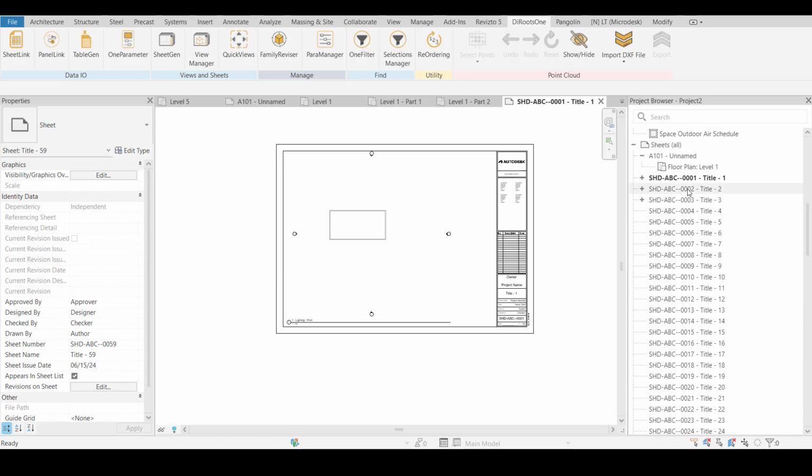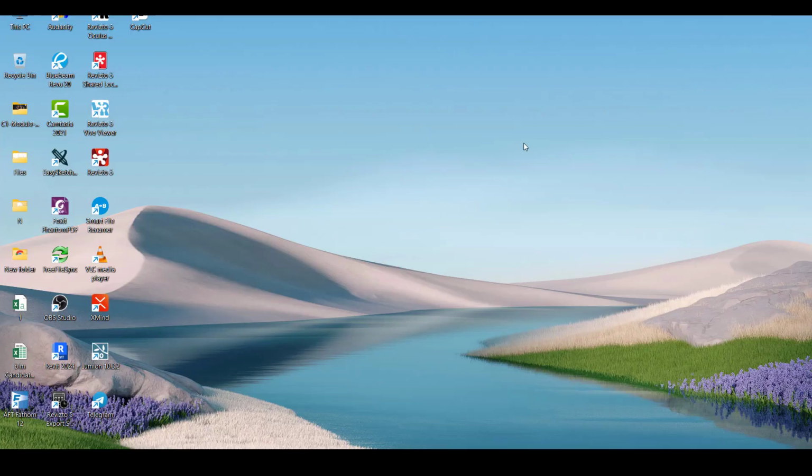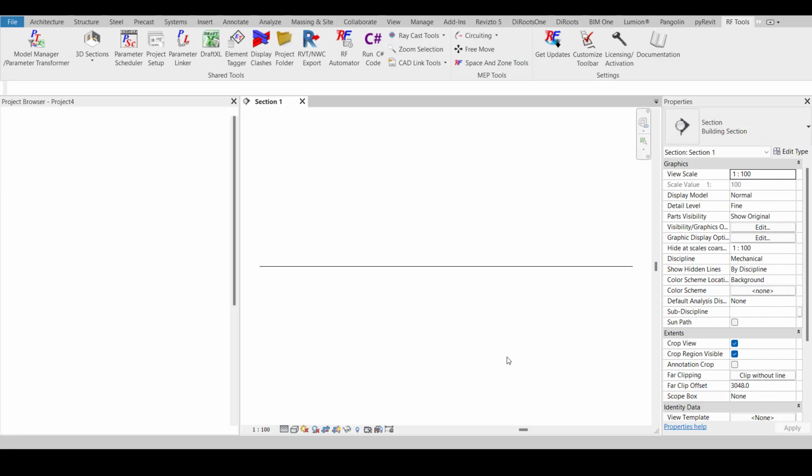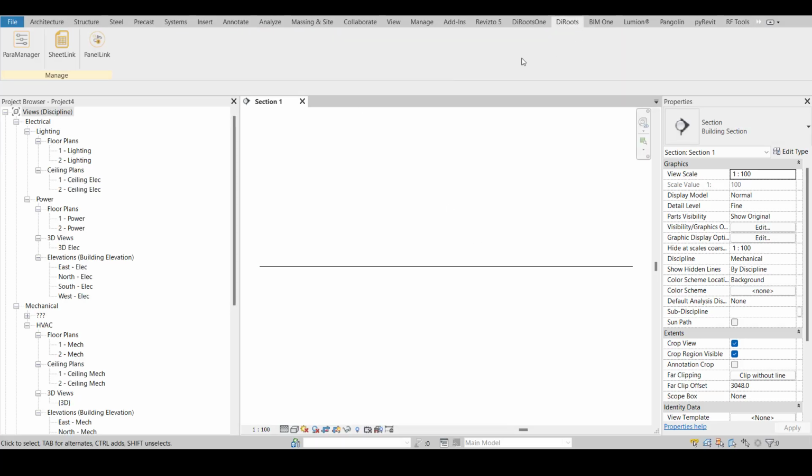Okay, and all created with a complete title and drawing number. Drawing number you have to get it from the drawing register, which you have created already in Excel. You just copy and paste in this one. Don't try to import your Excel file directly in Revit. It will not work. Okay, in this Dynamo.